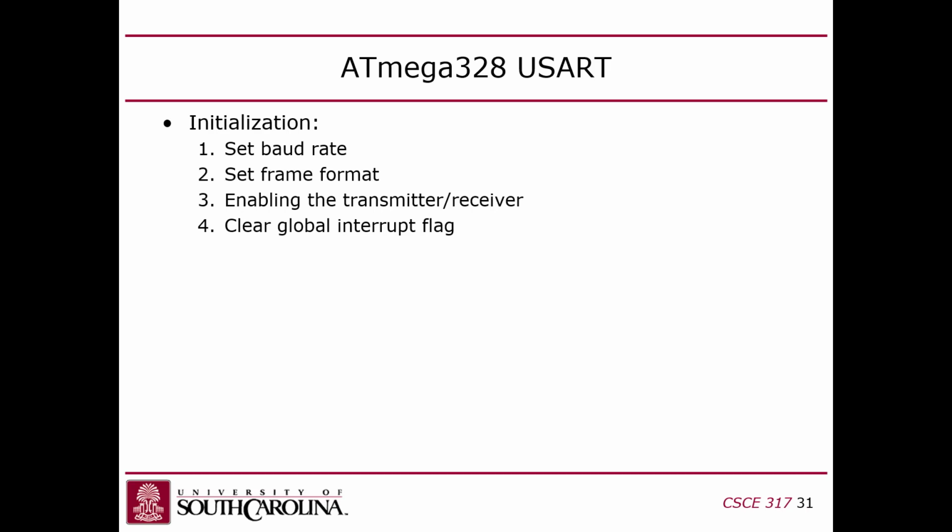Okay, so how do we use the UART on this chip? Well, one way is to use the GPIO. You can write code that will use the GPIO pins. You only need 1 of them to transmit and 1 to receive. So with 2 GPIO pins, you remember you've got 23 pins, you could implement UART, or your other option is you can use the built-in UART.